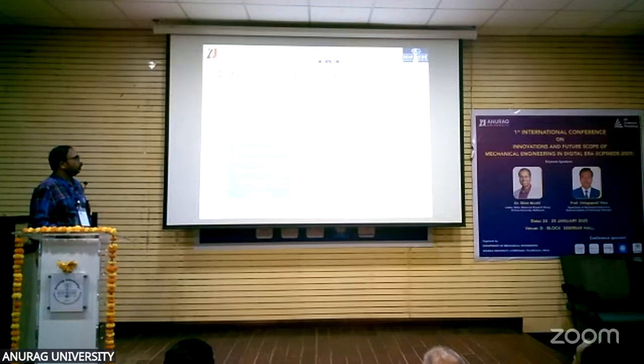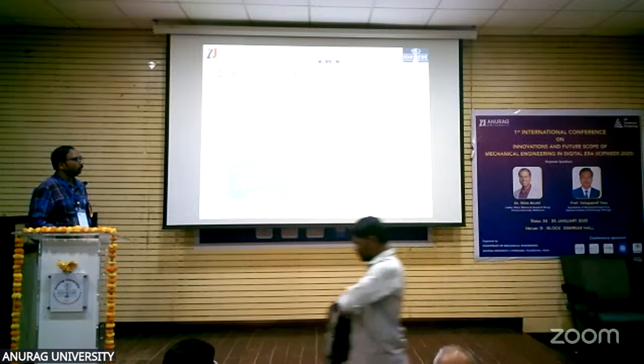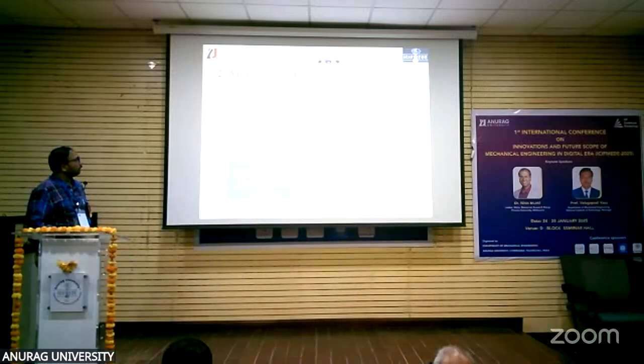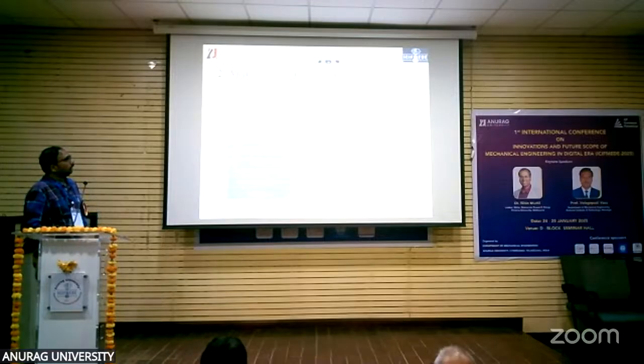I have used three process parameters, MWCNT content, cutting speed, and feed rate, in the range of 0 to 1 weight percentage, 25 to 75 meter per minute, and 0.1 to 0.2 mm per revolution. In the modified Taguchi approach, for nine experiments with 3 levels we need to get 4 parameters.